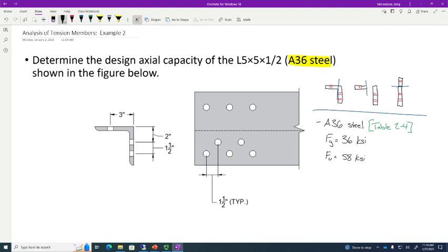Okay. One thing I'll mention, and I haven't really talked about this, and in most cases this won't be a problem, but if you notice in the manual the grid next to all of the steel grades with the white, gray, and black squares, the black squares correspond to preferred material specifications, right? So what is the preferred material specification for a W shape, as an example? A992. Okay, A992 is the most common grade of structural steel that you will find W shapes in. The point I'm making is there may be a problem where I just say pick a W shape, and maybe I don't give you the material grade. That is a very good assumption for what the material grade could be, okay?